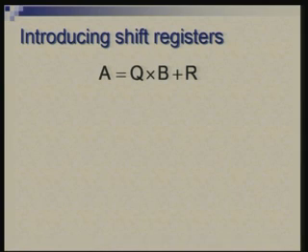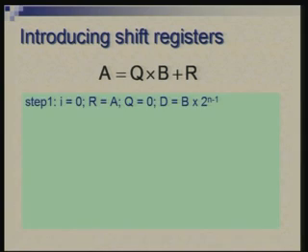Now, in the algorithm which I had written, we were talking of d multiplied by 2 raised to power some factor. Rather than every time multiplying by that factor, we will shift it step by step, as we did in the case of multiplication. Of course, the directions of shifts may be different here.